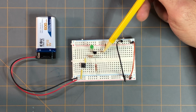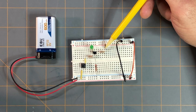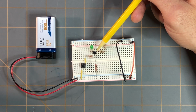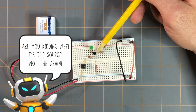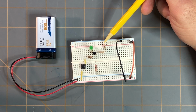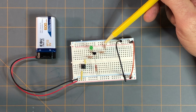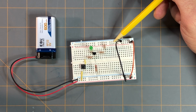These are two 100 ohm resistors that when set in series add up to 200 ohms. So that drain lead of the MOSFET is in line with this lead of this 100 ohm resistor, which is in line with this 100 ohm resistor, making up 200 ohms together. And the end of this resistor is in a point on the negative supply rail of the breadboard.